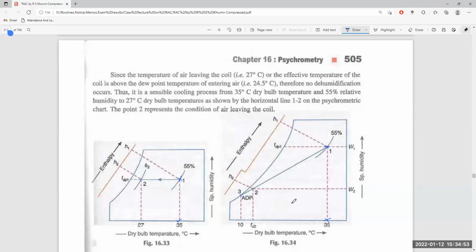This is the saturation temperature at the partial vapor pressure of the incoming air. It means if we reduce the temperature a bit below this, moisture will fall out and the humidity content will be reduced.